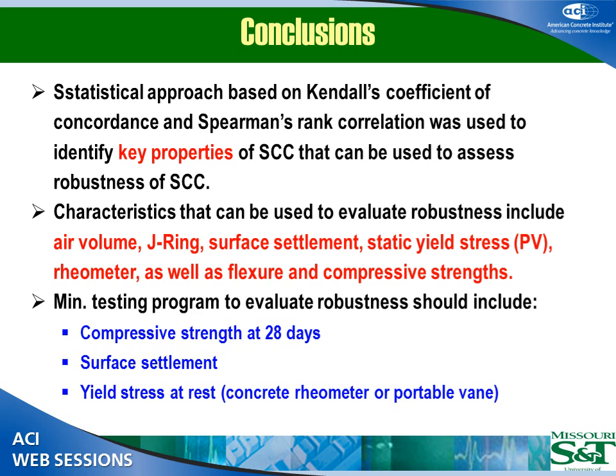And this is what Dr. Rousset was talking about, that within plus or minus 10 liters. And the superplasticizer, if you're using a superplasticizer, say at 0.6, 0.5 liters per cubic meter, so you're looking at about plus or minus half a liter, which is within the precision, if you would. Okay, thank you. We could make it a lot higher, but we want our SCC mixtures to be better, with tighter control, and that's what they need.